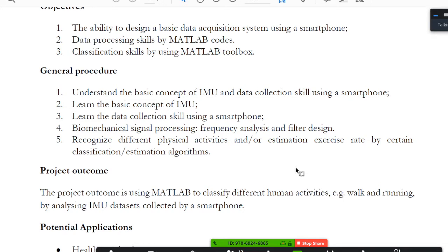It's a very special one. No one can teach you a very general way to do it. For example, you can just use peak detection to detect the rate. When you get the peaks, you calculate the distance between the peaks, and then you know the rate, right?